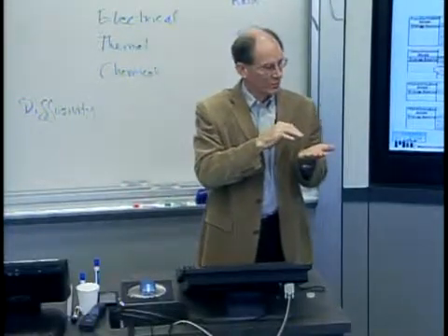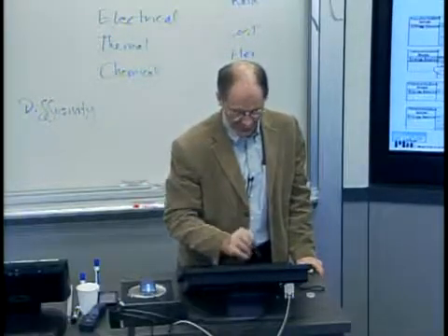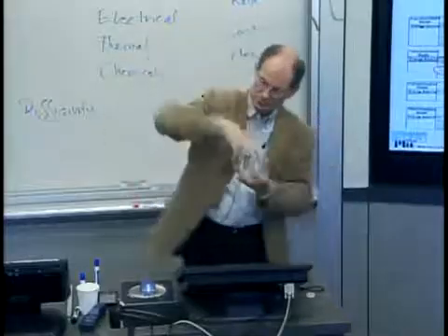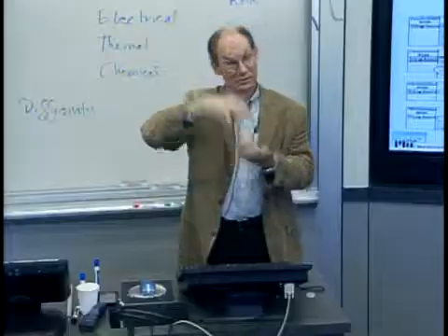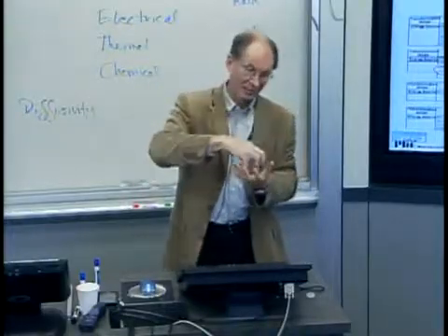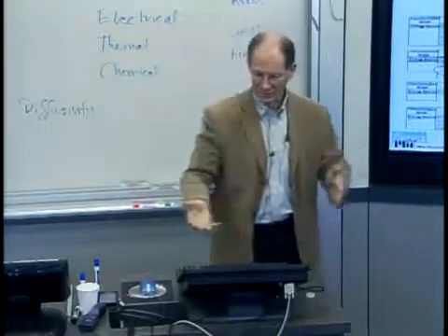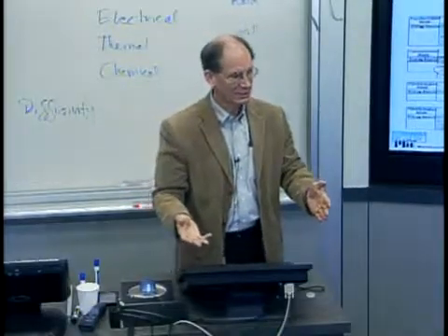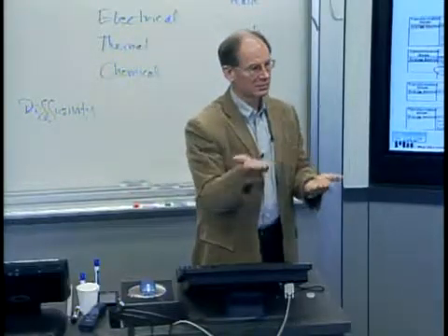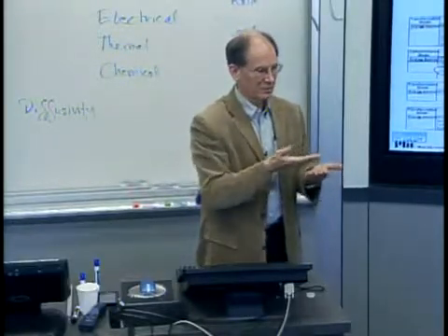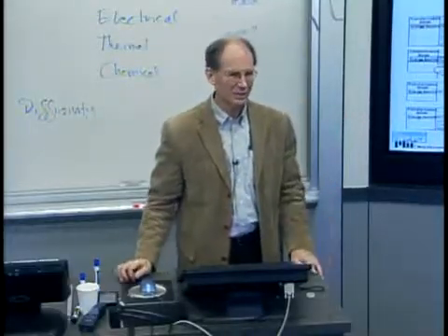Now it becomes a serial process. And think about the difference between these two processes. If I've got this big press that has to push this powder into a green compact, that's a big piece of equipment and an expensive tool, whereas 3D printing is a desktop thing. There are desktop versions of it. All I have to do is type in a CAD file. It does a section file of it, creates this thing, and I've got essentially equivalent parts. Not exactly equivalent, essentially equivalent parts.